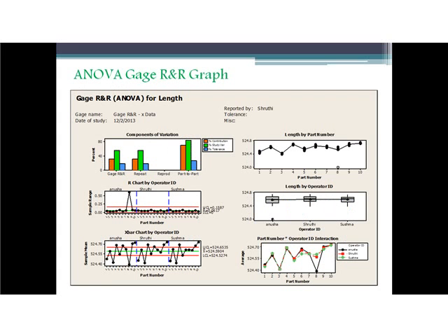Coming to the gauge R&R graphs. The first is components of variation. Here each cluster bar represents a source of variation. By default, each cluster bar has two bars, one with the percentage contribution and another with the percentage study variation. If you add a tolerance or a standard deviation, a bar of percentage tolerance also appears.